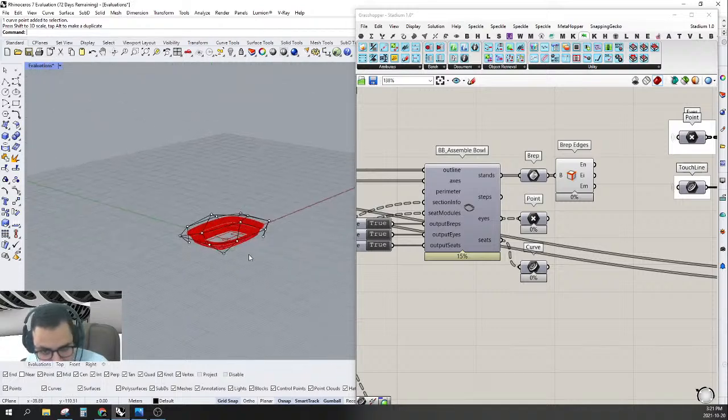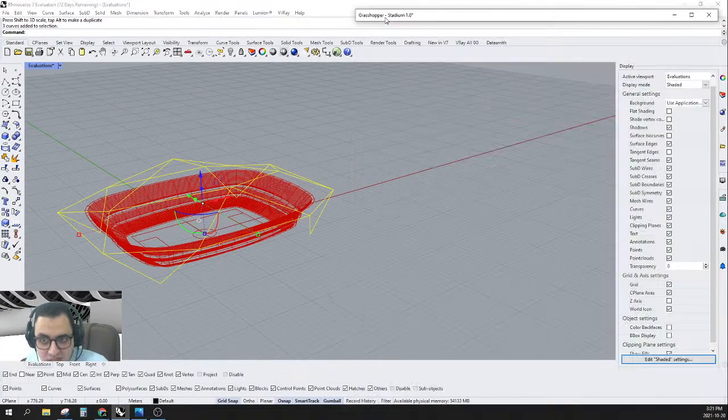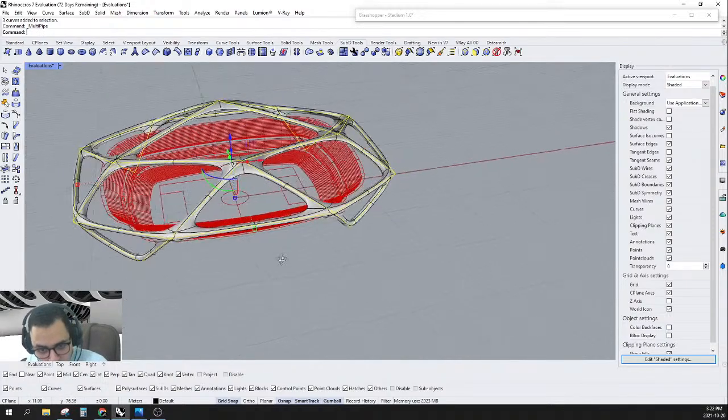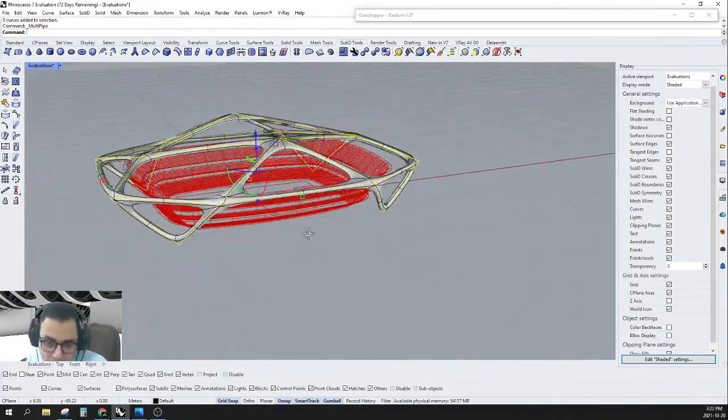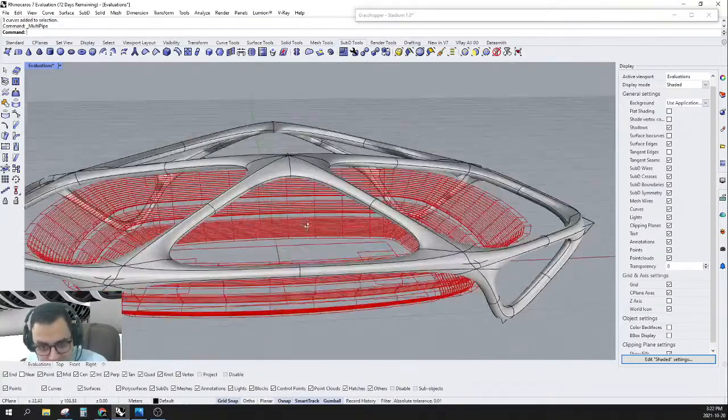And after you finish what you need, you can simply go to the sub D and select the multi pipe, set multi pipe like this, and 2, and enter. The division is 1. I will show you why 1. So now we created this thing right here.